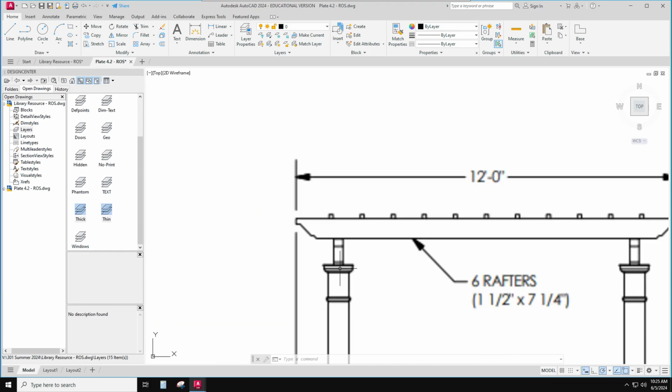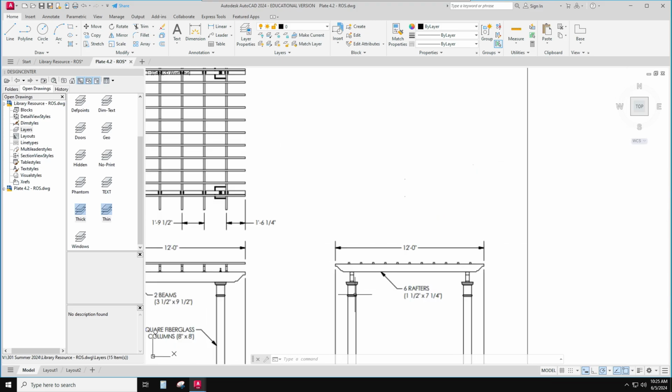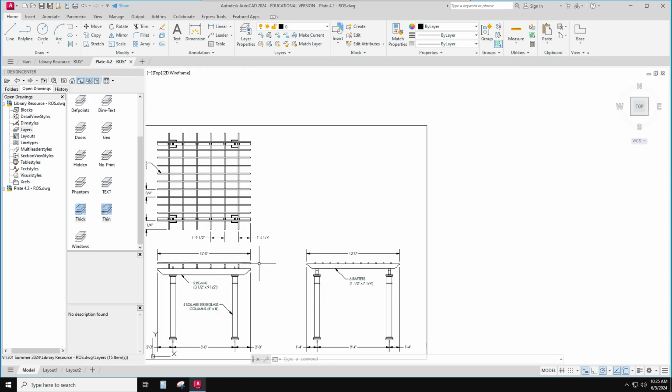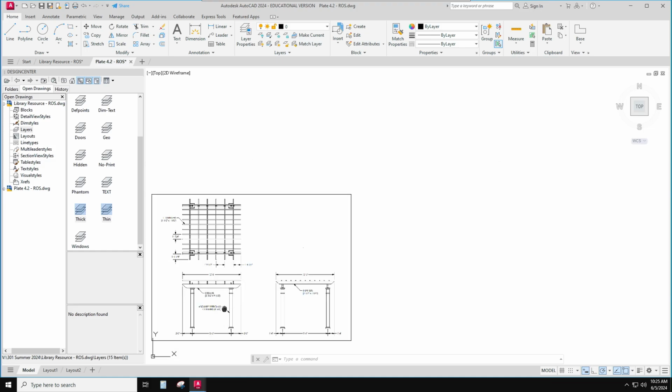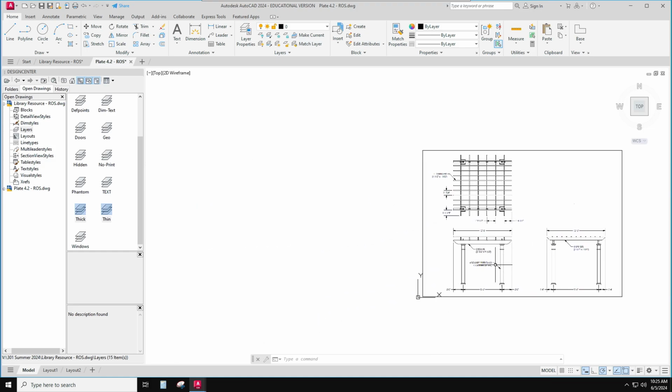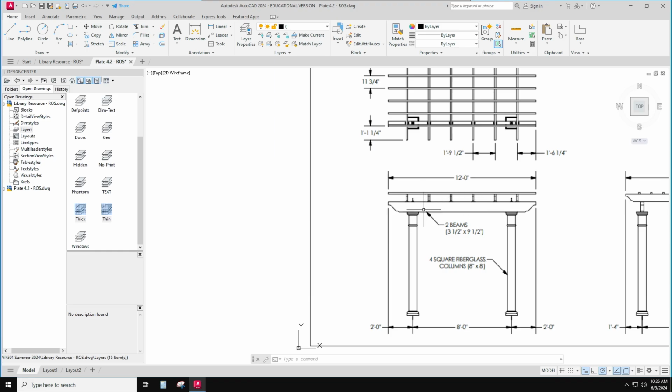And it doesn't really give us much information about what these little things look like, so you'll just draw an estimate of them. This is also a bolt. I don't think you need to show the bolt. And it gives you some spacings and things like that. So we're going to draw that. And we're going to start with the end view. And I'm going to start with the columns.